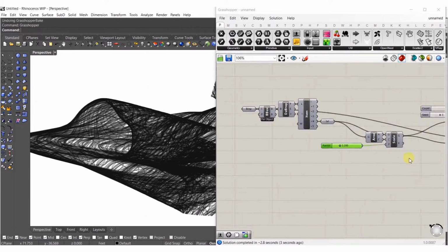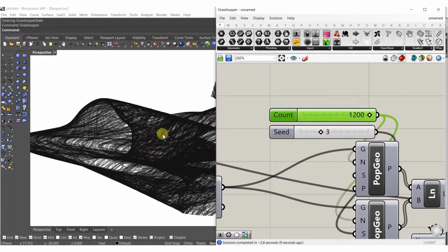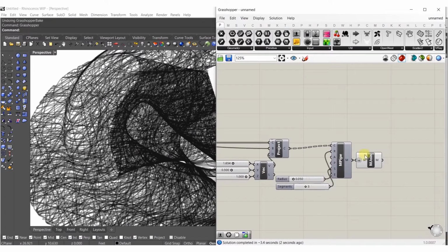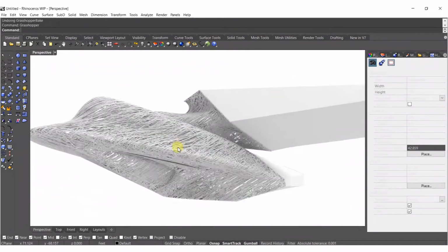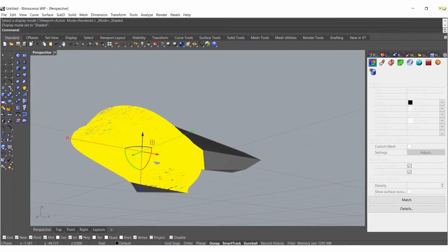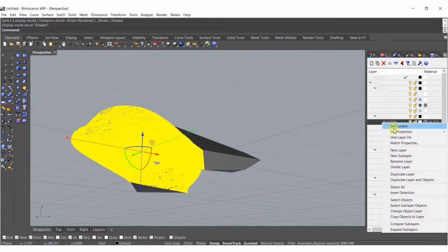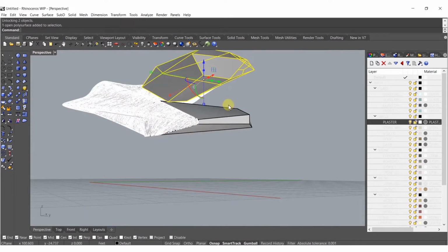All right. So from here, what I'm going to do is just change the materials as usual for Lumion. And I'm thinking that's going to be some sort of white kind of thing so we can see it clearly. And these, let's make them wood maybe. So I'm going to type in offset surface for each one of these. And let's just do the distance of 1. Give them just a bit of thickness. Let's wait for it. Oop, turned out a little crazy. All right, let's flip them maybe. It might not honestly matter in the end.